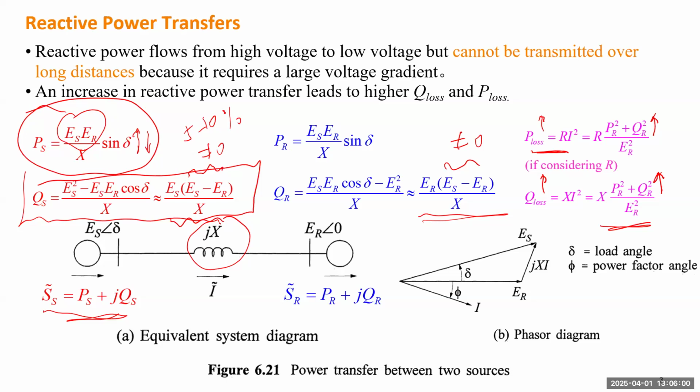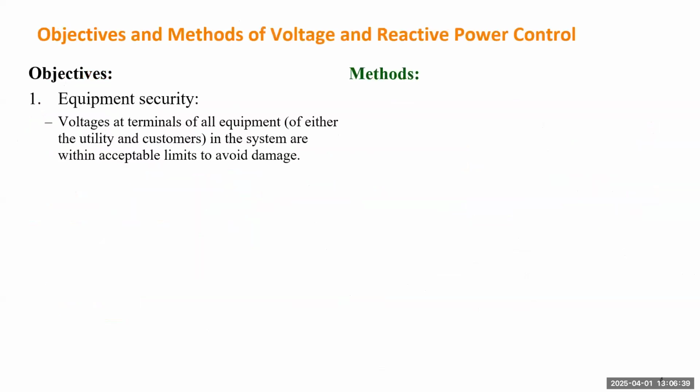So if you think about it, in the power system, you have a short circuit, and that lasts for a long time to make voltage close to zero, which means the active power cannot be delivered beyond that point. Because when you get to that point, this term will be close to zero. So it's like you create either a wall or some black hole, so that the power cannot pass that point. So if you can make sure voltage everywhere stays at about 100% of its expected value, you can safely deliver active power to any location. So that's the secondary objective of voltage control.